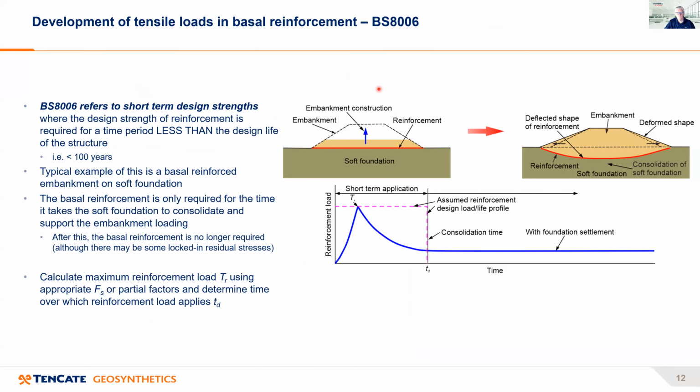So coming back to the slide that we saw before, where we have the maximum load in the reinforcement over the consolidation period of the soft foundation soil. While in analysis this may be really what's happening, the blue line, from a design point of view we simplify that and assume that the maximum load remains constant with time up until the consolidation time, and then it drops off to naught. So we make a simplified assumption from a design point of view.